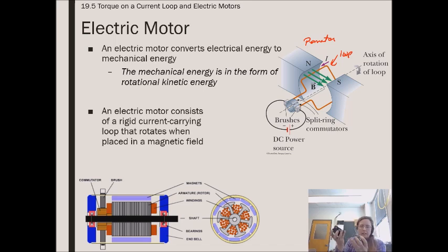So I'll have motors in class that we can take apart, but here you can see the windings. It's not the nice square that you see on the picture. And you have the magnet. This one, the magnet is in the center, which you don't need brushes, because brushes are used to get the electricity from the stationary outside world to the spinning inside world of most motors. This one happens to be a brushless one because it's the magnet that spins.